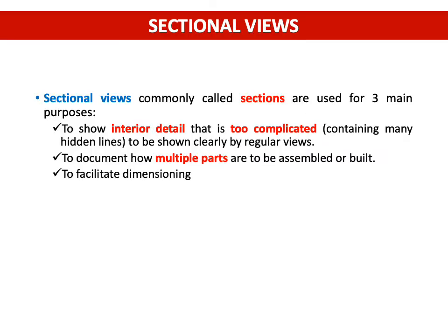Okay, so the importance of the sectional views is there are three main purposes. First is to show the interior details. If the object is too complex or too complicated, where you have too many hidden lines, it is much easier and much clearer to see the interior details. Second is to document how the multiple parts of the object are assembled or built. And thirdly is for dimensioning.